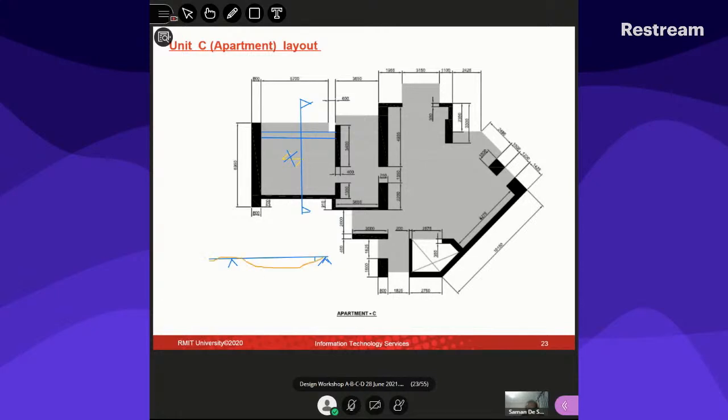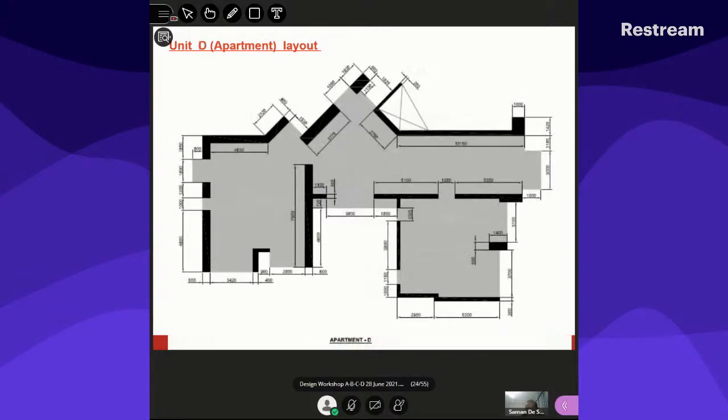Now, if you deflect like that, sometimes you'll find this tip is actually trying to go up, because the backspan is so large, and therefore this tiny little segment here, maybe 500 millimeters, or at best a meter, means this cantilever is not struggling at all, which is exactly the same situation. But in this case, I think you have to do a one-way span slab.